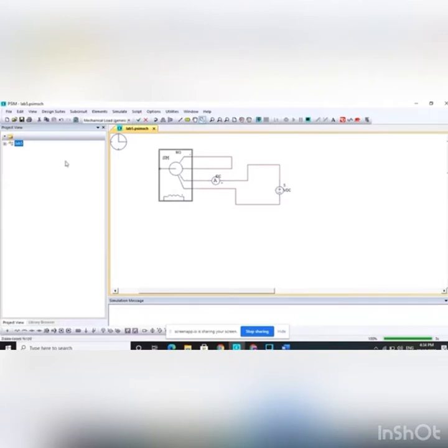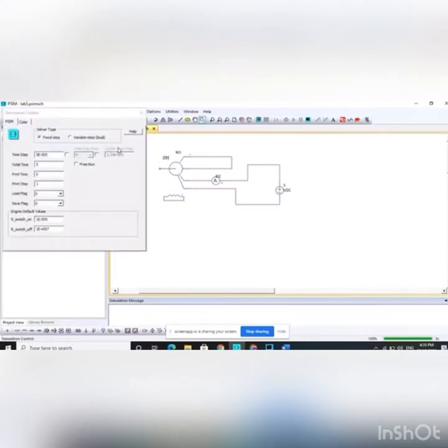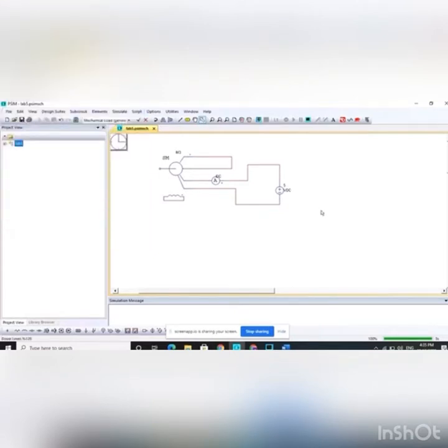For the simulation control, we set the time step to 0.0005 and the total time to 5 seconds. For the DC voltage, we set 5 volt, 10 volt, 15 volt, 20 volt and 25 volt.